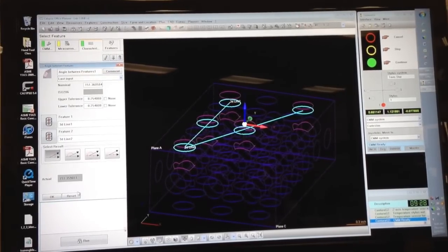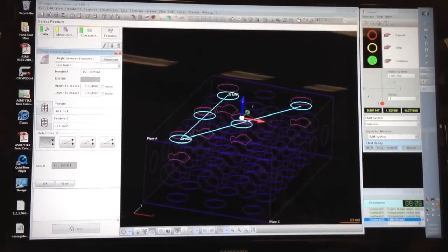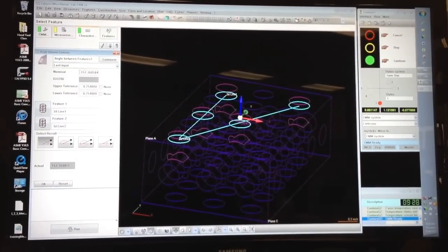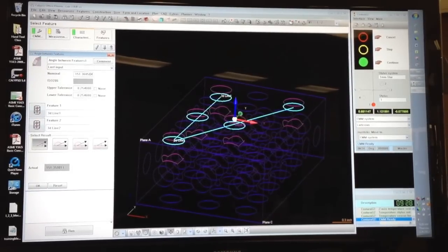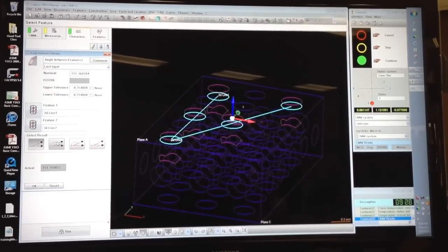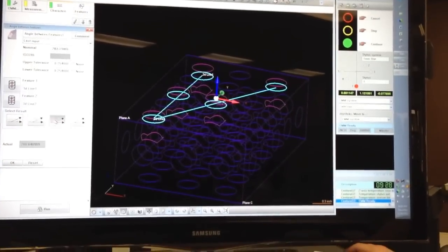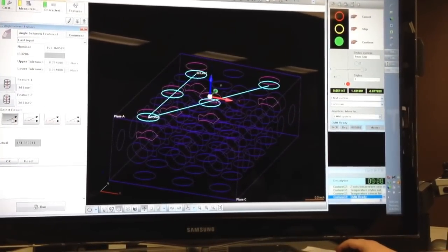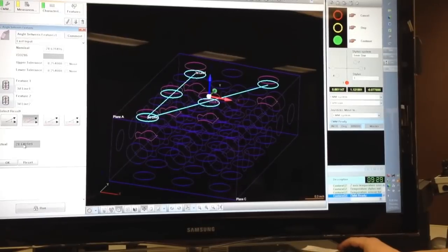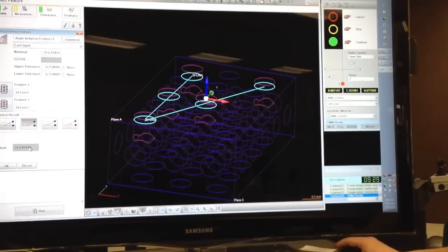Now the target value that I'm looking for is 28.6 degrees. And I can clearly see that this is some kind of complementary angle to 28.6 degrees. So what we have are 4 buttons here that show us the 4 complementary angles that are possible when two lines intersect. For most people, the easiest thing to do is just click the 4 buttons until you find an actual that is very close to what you're looking to measure.